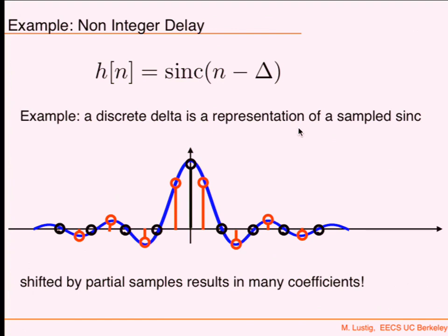Okay. A similar phenomenon happens when we compute the DFT of some sinusoid. At some sinusoids, I'm going to get deltas in the DFT. But if I just shift the frequency of those sinusoids a little bit so they don't align with the integer, I'm going to get a periodic sinc. Okay? So it's a similar phenomenon in that sense, because I think of things as representing discrete time sampled band-limited signals.